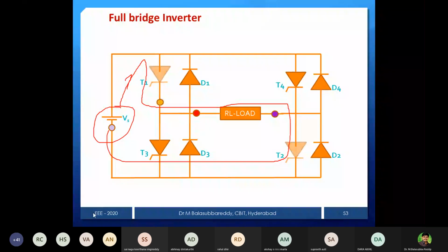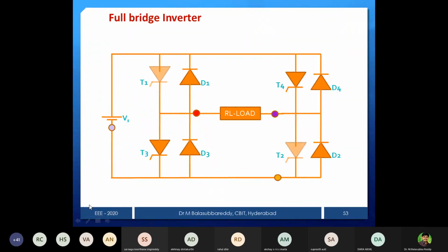And now you can see how it is going to operate. Initially T1, T2 are conducting. Now, for a resistive load, the diodes do not come into the picture. Whatever T1, T2 conduct, if the on duration is over, T3, T4 will fire. That's all. But now for the RL load case, the inductor will store some energy, and to dissipate that, it has to fire T4 and D3 and D4. Now we'll see carefully how the current direction moves.